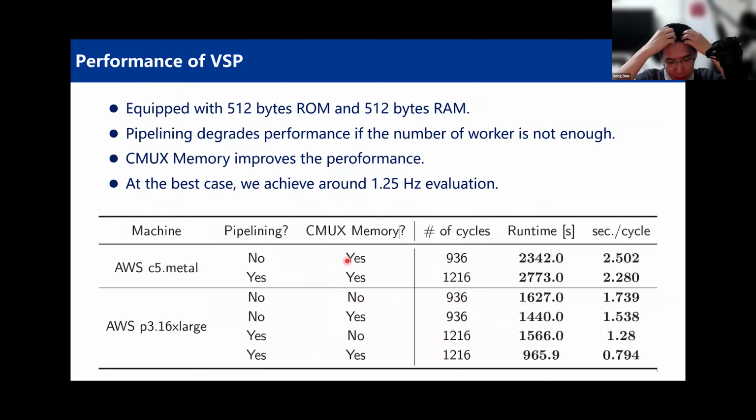Anyway, before getting into this, this is basically the results page for our processor. And before explaining the results, I'm just going to make two remarks on why this thing runs slow. It runs very slow, but why? The first problem is, and both of these problems come from the fact that we don't see the comparison results, right? Because we cannot see comparison results, our processor executes every instruction in every cycle.